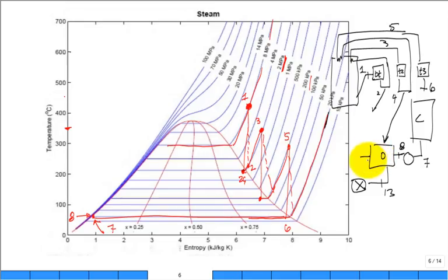Where is this state coming out, at state 9? I'm going to pause and walk around. You should be able to put state 9. It's a little more challenging than all other states. But where exactly is state 9 on this TS diagram? All right, so a lot of us had it. It's saturated liquid at that intermediate pressure, the low intermediate pressure, which was the 200 kilopascal. So state 9 comes in right there.